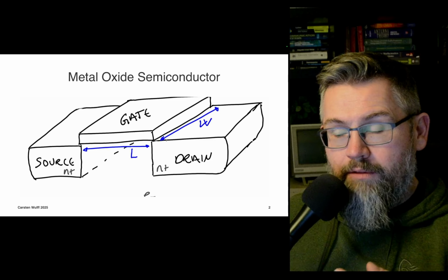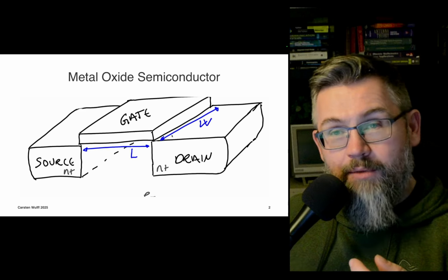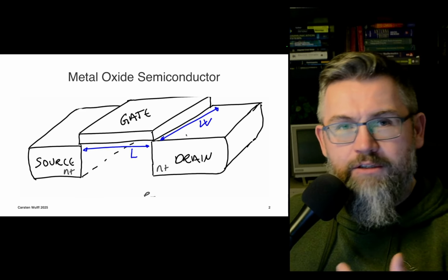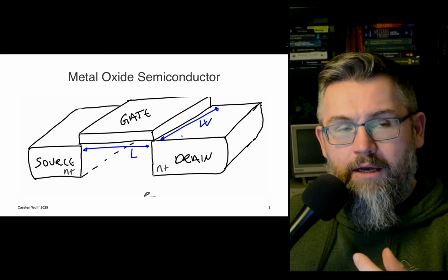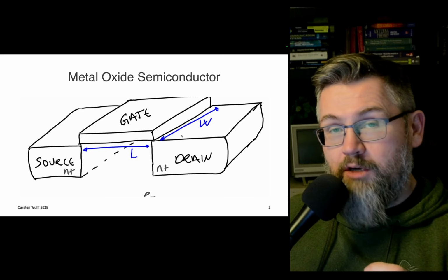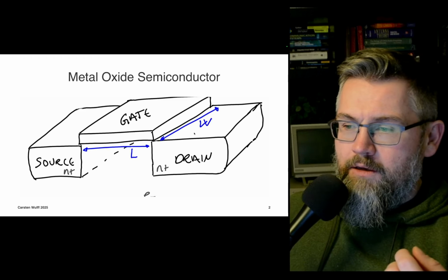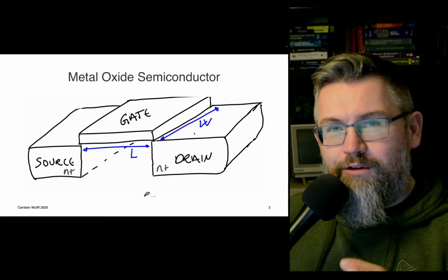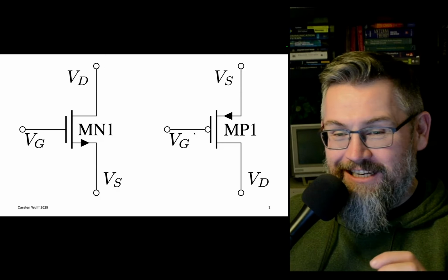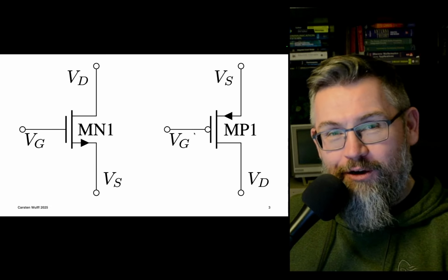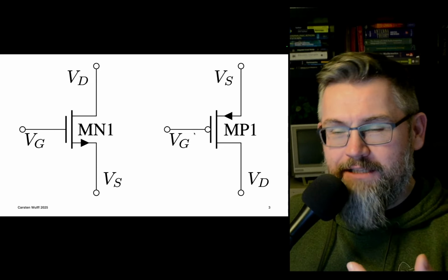And for the transistor width, it's, well, how wide is the gate or the drains, basically. Now, a wider transistor gives you more current. So, as an analog designer, we can play with both the length and the width to adjust what type of current we need and the conditions that we need from our analog circuit. So what I'm going to do is start slowly and give an opportunity to at least understand a little bit how MOSFETs work, and then we're going to go more deeply into the quantum mechanics, or maybe not quantum mechanics, but at least the effects of quantum mechanics.